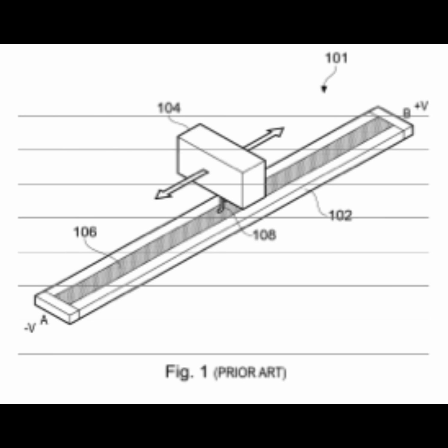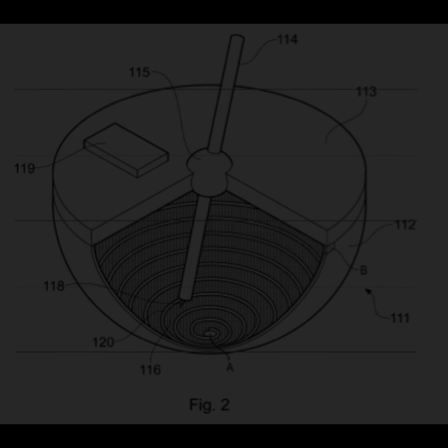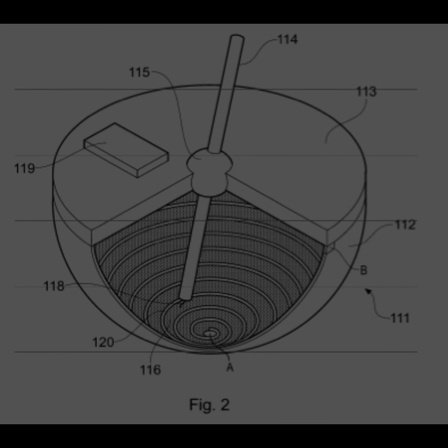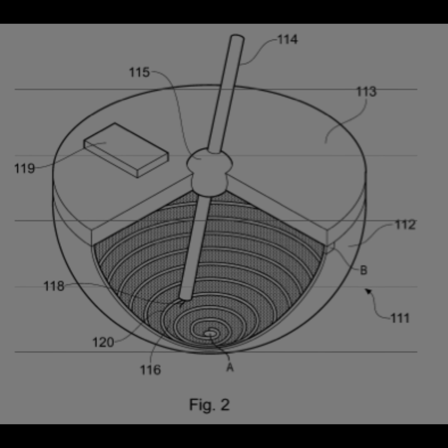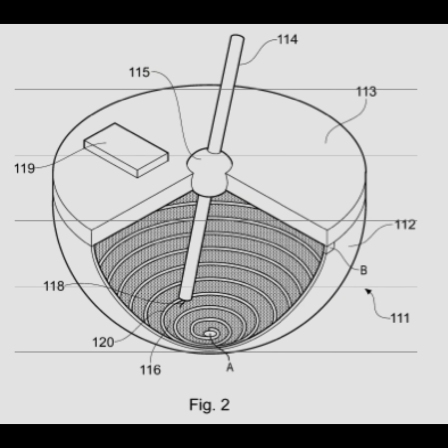As shown in Figure 1, a joystick 1 according to the invention comprises a hollow, hemispherical, and electrically insulating support 2, which is closed by a cover 3. An actuator 4 is pivotally mounted at the center of the cover 3 by means of a ball joint. The ball joint comprises a ball 5 arranged on the actuator 4 and a socket arranged in the cover 3 for retaining the ball. Teaching note: this starts the first embodiment.